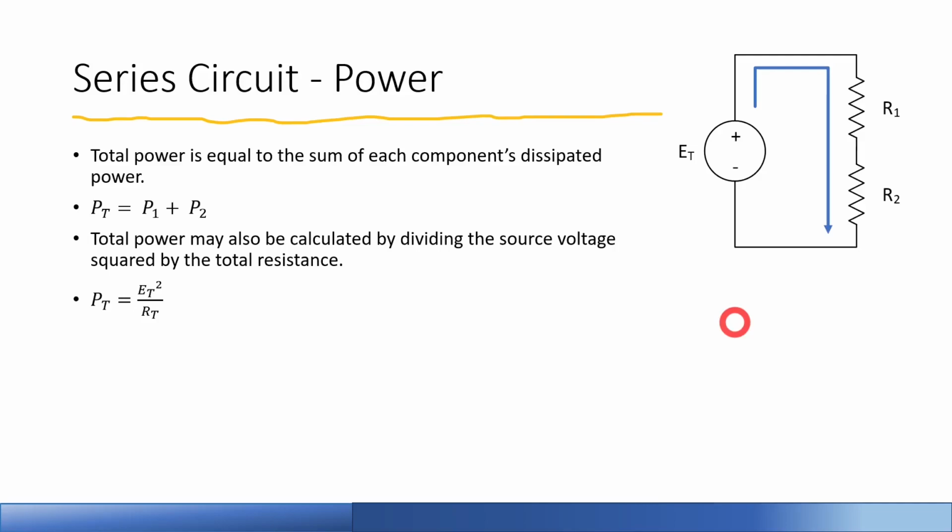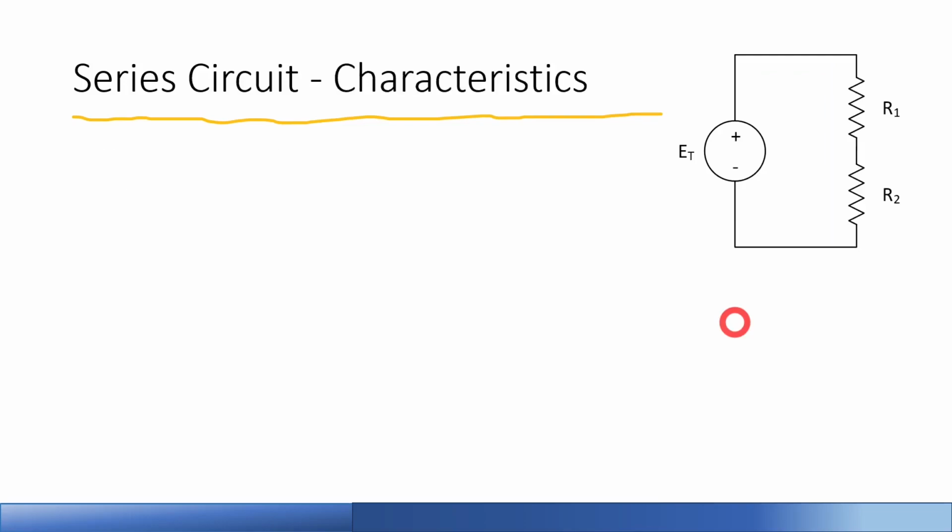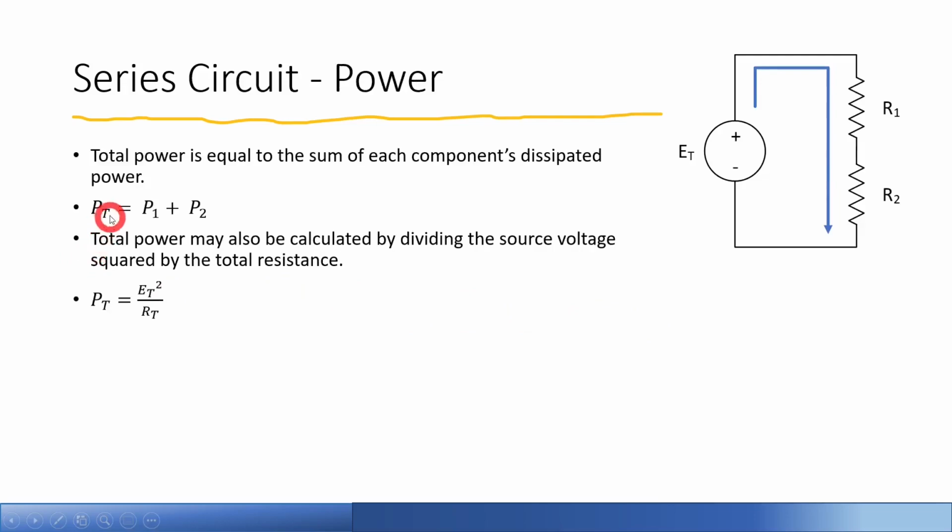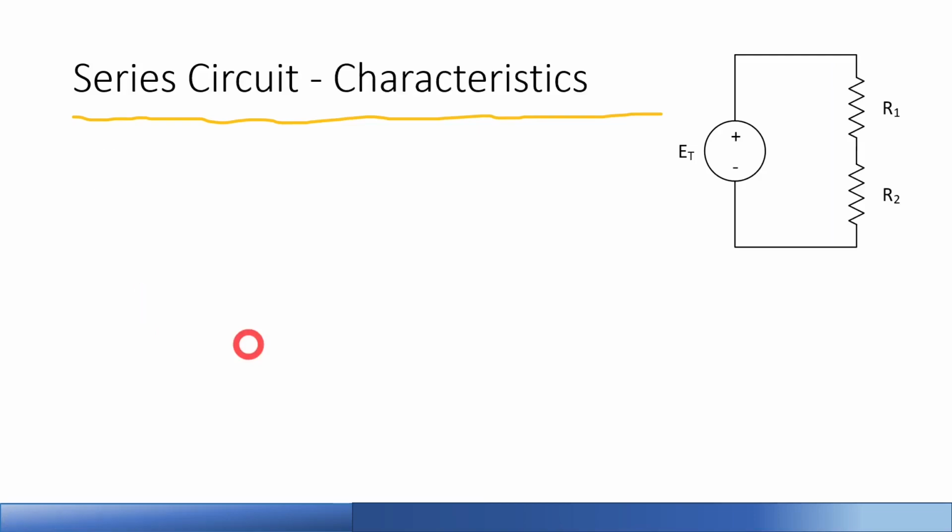And if we calculate it in these two ways, we can do a checksum on these at the end. So you can compare these two together and see if the sum of all the ones that you used current and resistance equal the sum of the total that you used with voltage and resistance.